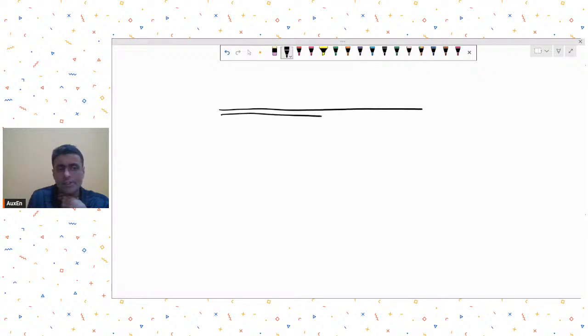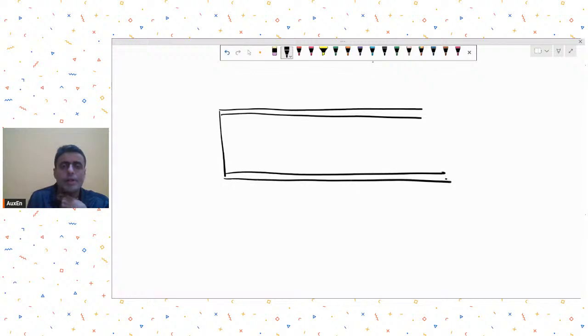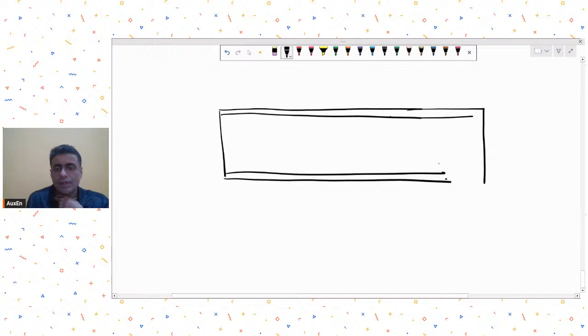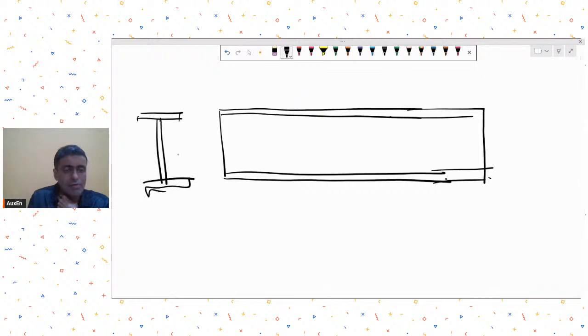The basic principle is this: let's say I have a plate girder like this, and usually in plate girders we have thin webs. If we have thin webs, there is always a chance that the thin web fails under buckling. So we will check this web for the web buckling effect, and accordingly either we will limit the load or we will provide transverse stiffeners, isn't it? This is the usual process that we do.